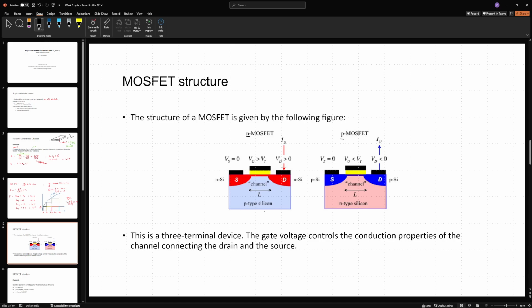So this is a P-type silicon substrate MOSFET, which is an N MOSFET because conduction takes place through a channel inversion. So this inversion layer over here, let me see if I can draw like this. Of course I can. So this line and this line right here. So these inversion layers is where the conduction takes place. Of course, we are looking at MOSFETs being worked in the enhancement mode, not in the depletion mode.